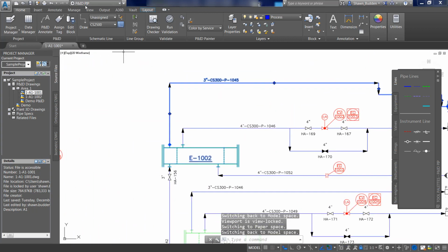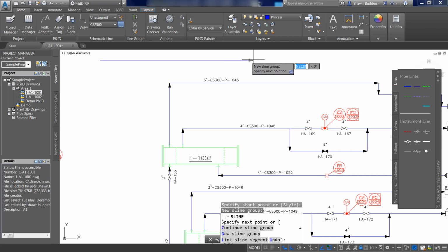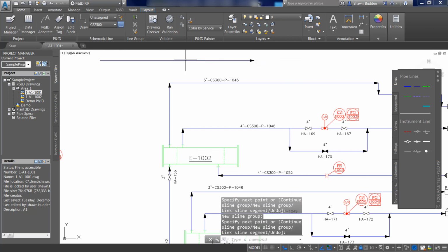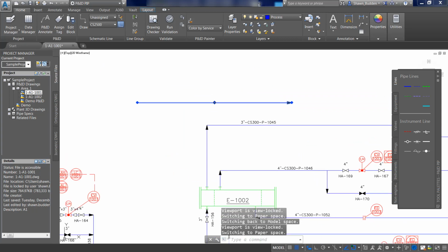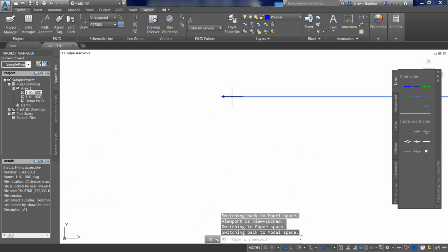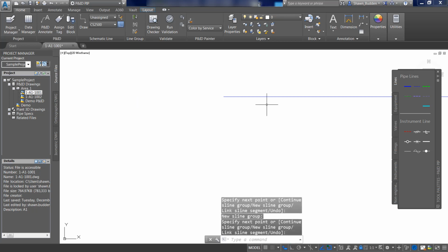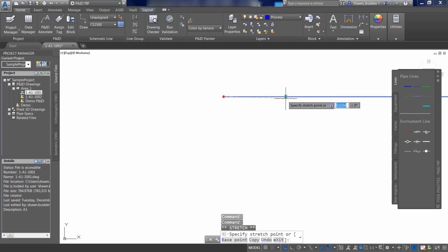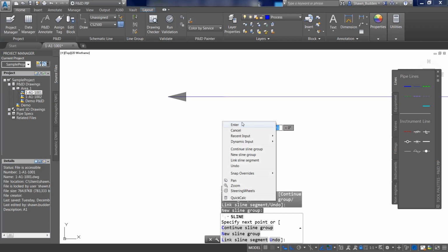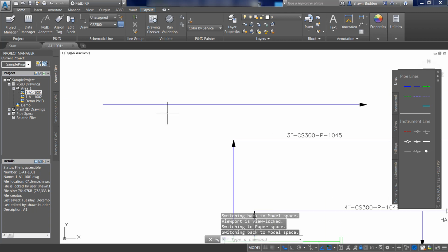Now, what I'm going to do here is draw another quick line right here. And when I do that, I'm going to select this line and you'll see that I have a grip at the end of the line. Now with this one, I can use that to continue, or I could actually shorten that line with that as well. Once again, you can still use the dynamic grips. You can put in a specific distance and angle, but you can use this to shorten or lengthen the line. So that's also another convenient thing that you can have, just using grips to move the line back and forth.